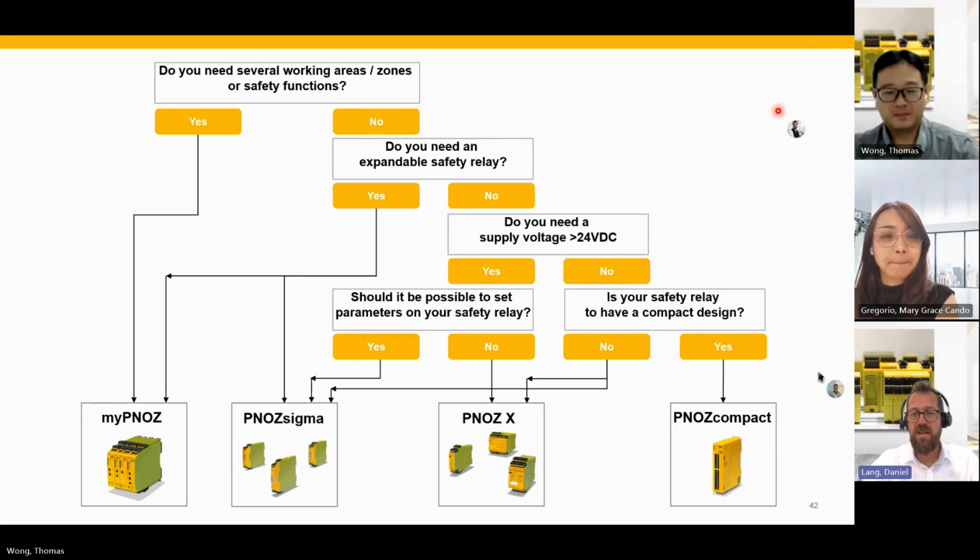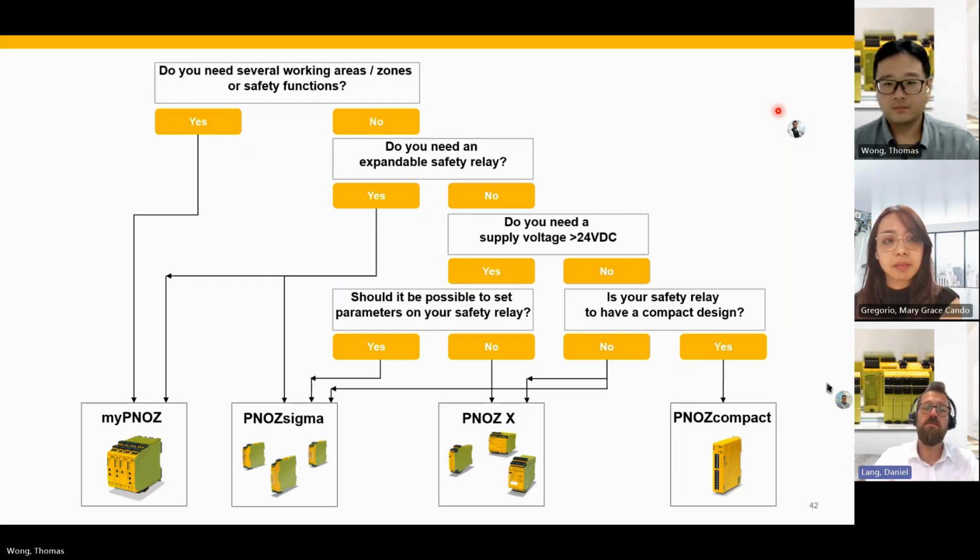Yeah, there are many, and as you said, there is an ocean of safety relays. In this case, as Thomas also said, you have to look at what you want to have at the input channel. Mostly you can say there are safety relays which are capable of emergency stop, safety gate, and safety switches in one, and then there is sometimes an additional safety relay which is doing the same but for OSSD input channels.